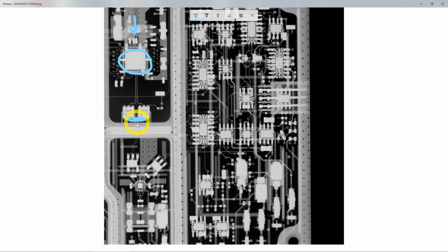If you follow that, you can see that it goes through the transformer and it goes in through this IC. Originally, I didn't know what that IC was, but now I do know what it is, because it has another transformer with a signal coming from the other side of the board from an identical IC like this one. That's obviously the reference coming in. That means that this is a phase frequency detector. The output of the phase frequency detector is then brought over here and is given to these op-amps, which are then processed and create a charge pump.